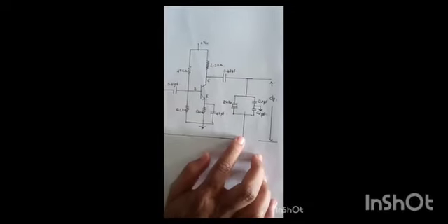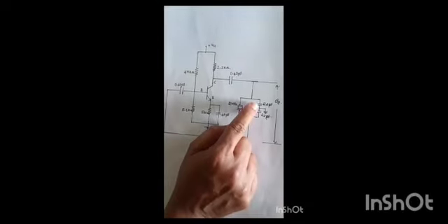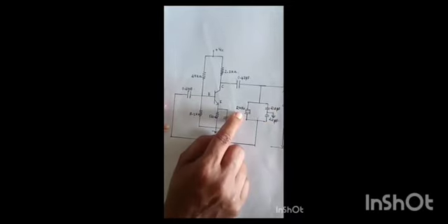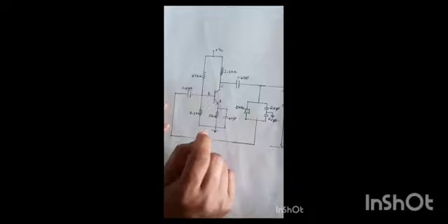We also designed the capacitor values earlier, where we were using 1 nanofarad and 2 nanofarad. In the crystal oscillator circuit, we are taking the capacitor values as 22 picofarad and 22 picofarad, and the crystal we have taken as a 2 megahertz crystal. Now we'll do the rig up of this one.